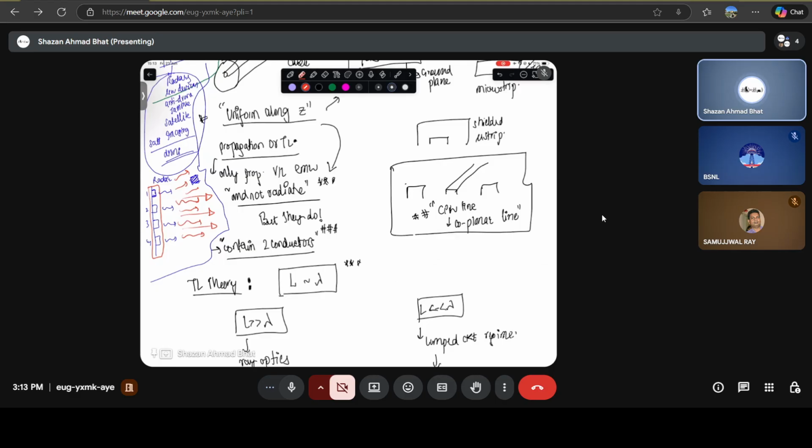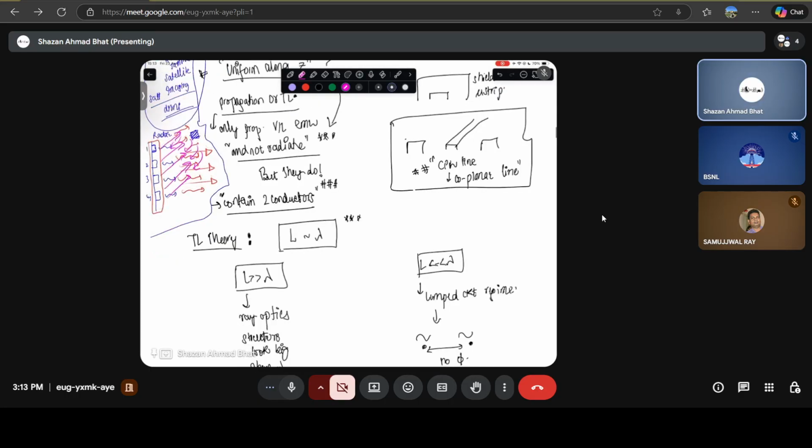Now what is basically happening? You want to tune the directions of the electromagnetic waves in such a way that they are mostly in this particular direction, so that when you get the reflection back, they will be detected with higher efficiency. How do you do it? You can do it by simply turning the entire antenna, right? This entire thing can be turned like this, turned like this, and it's going to emit the microwaves in this particular direction where it is going to hit the objects and you are going to get the reflections back.